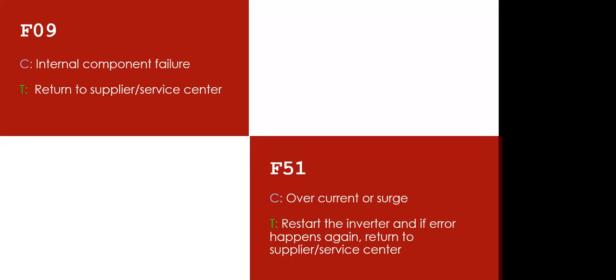The same thing applies to the DC surge protector. If you want to protect something of 250 volts and you went ahead and used a 600 volts DC surge protector, you know that you are not protecting anything, because you are using 600 volts to protect 250 volts.